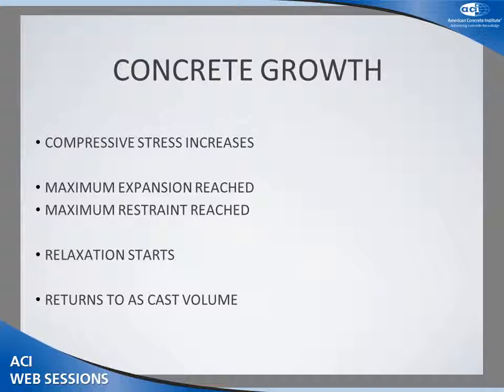Since the expanding concrete is bonded to the reinforcing, the concrete is trying to stretch that reinforcing. The reinforcing is much stronger than the curing concrete and resists the concrete expansion. The result is that the reinforcing transforms the expansion stresses into a compressive force in the concrete. And instead of physically expanding, the concrete is restrained and a compressive force is being built up in the concrete.